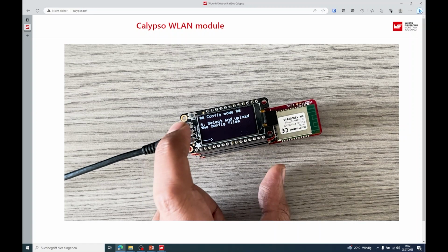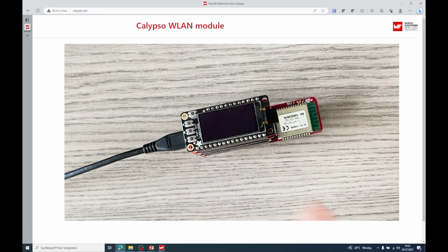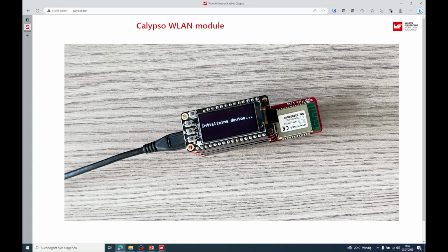Once this is done, click on Reset and allow the device to go through the process of connecting to the device provisioning service from Microsoft, getting the credentials, as well as finally connecting to the IoT Central platform. This might take around 30 seconds. As you can see, the device is now connected to the device provisioning service and it is trying to get authenticated. Once the authentication is done, it will connect to the correct IoT Central platform. As you can see, at this step, the device is already connected to the IoT Central platform.